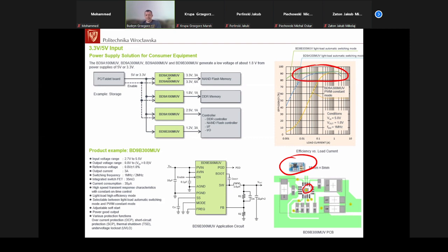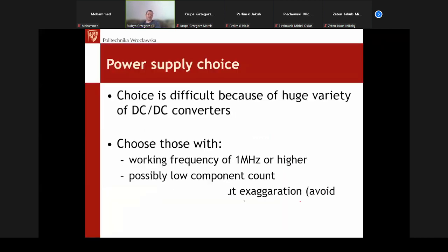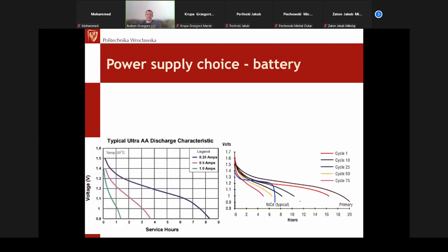Even in this super tiny case, the thermal pad is exposed and you can solder it, but then the problem begins: the case is so small that the thermal pad and the copper around it have to be large enough to dissipate the power inside the case. So you gain on a super tiny case, but then you lose on the area that you have to sacrifice for heat dissipation, for the radiator.